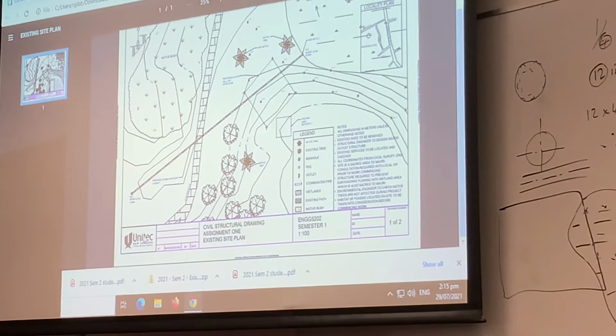So if you really want to start the semester by getting up my nose, make a path on your home computer saying C drive, I don't like Roger, civil drawing sucks or whatever, and I'll see that on there, and in the end it will say Unitec logo.jpg, right? And the same thing will happen when you bring it in here to Unitec. If you haven't got the logo in the same folder as the AutoCAD drawing, it'll come up with that path and you won't be able to see it, okay?